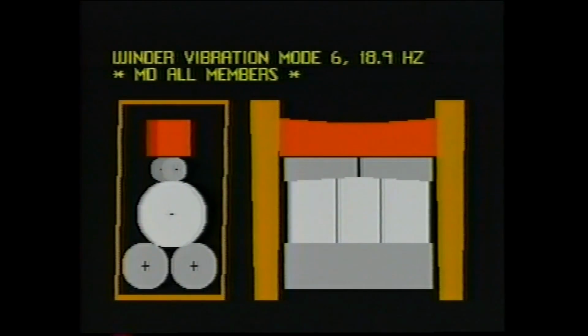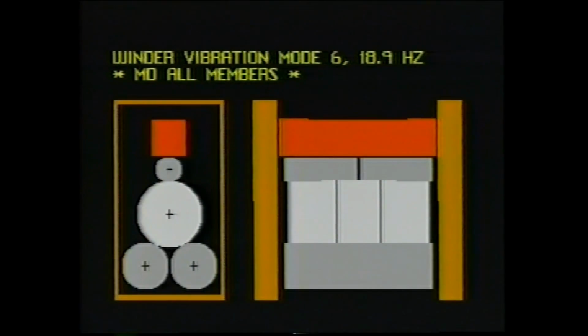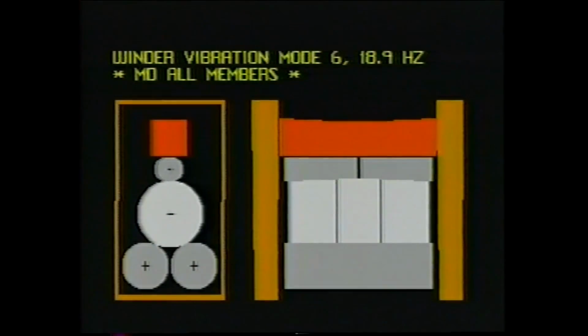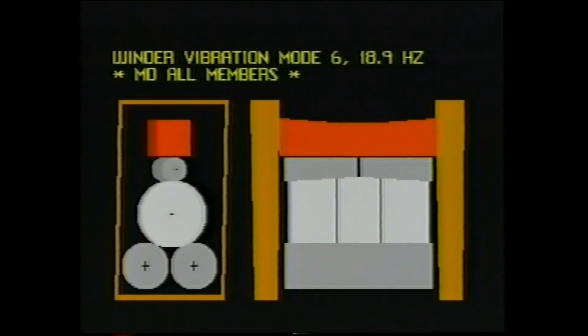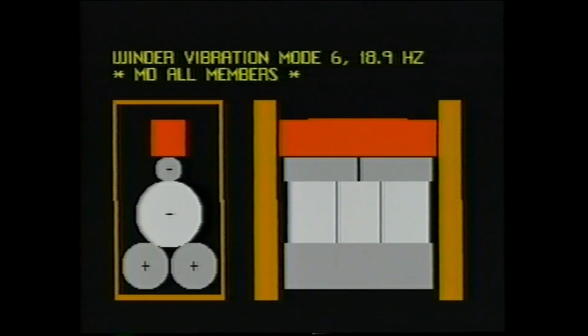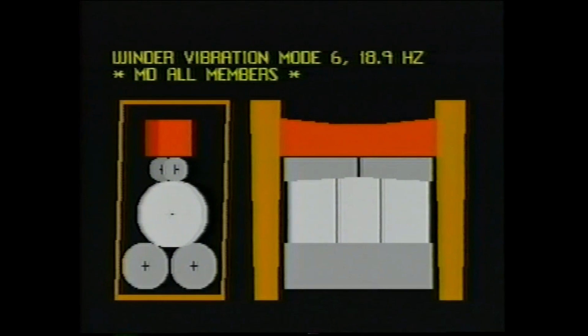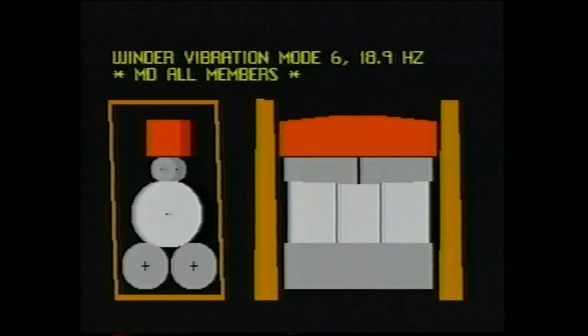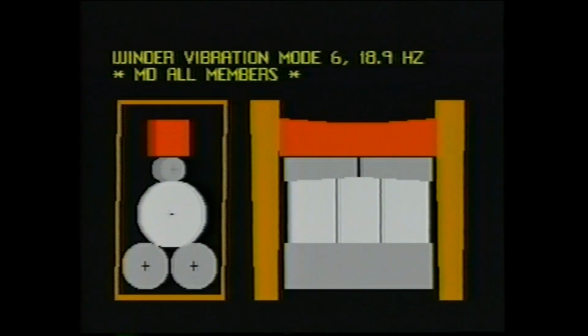This first of many complex mode shapes involving out-of-phase movement of components is extremely difficult to excite to large amplitude because strong forcing functions are rarely directed in two opposite directions at the same time. Additionally, this mode, which involves nearly all winder components, would require tremendous forces in order to move so much mass to significant velocities.